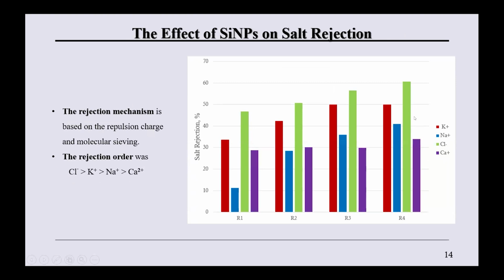The salt removal order was chloride, potassium, sodium, and calcium last. So we notice that membrane R4 is the optimal membrane for more investigation and testing.